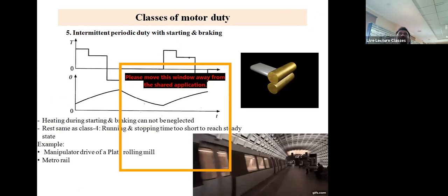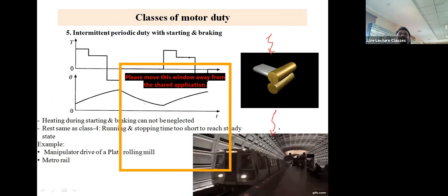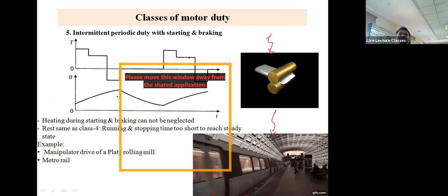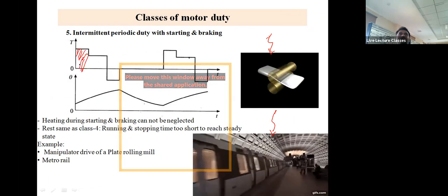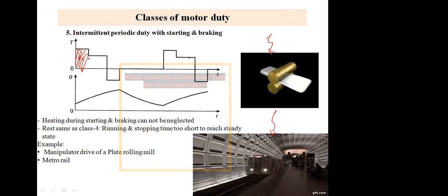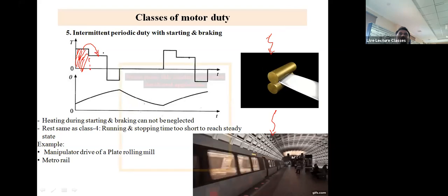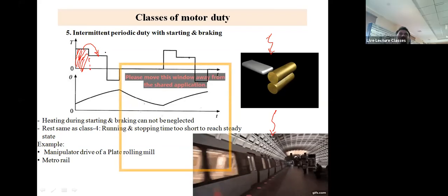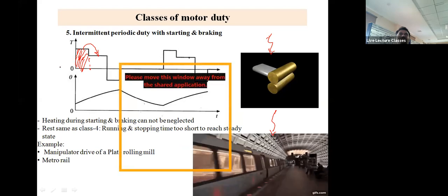Say what about these types of loads? These types of loads are like electric trains. When they will start, they will take a huge torque, right? And after it has started, it will require a lower torque to run it. Is it not so? The starting torque is definitely greater than the running torque.